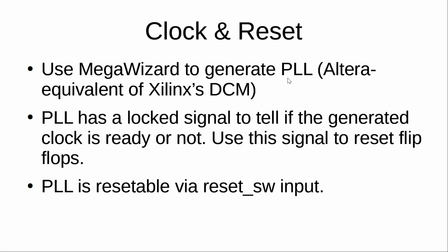The Altera equivalent of Xilinx DCM is basically this PLL. The PLL has a locked signal to tell if the generated clock is ready to be used or not. And we can use this locked signal as a signal to reset the flip-flops in our design. And this PLL is resettable via the external reset software input. This is the hardware switch connected externally to our SoC.